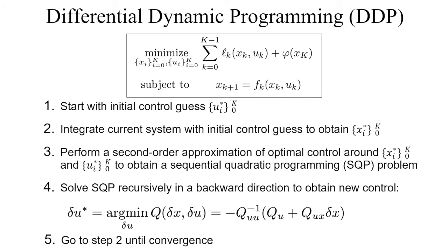In this slide, let's introduce the approach to solve the optimal control problem, differential dynamic programming, or DDP for short. A typical optimal control problem can be divided into two parts, cost function and constraint. The cost function can be formulated as the sum of integral cost terms and terminal cost terms. The constraint is shaped by ordinary differential equation of the robotic system.